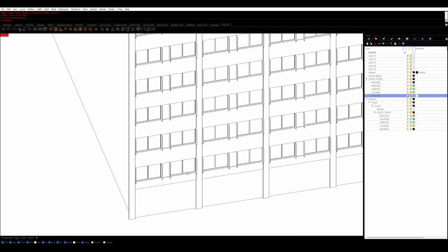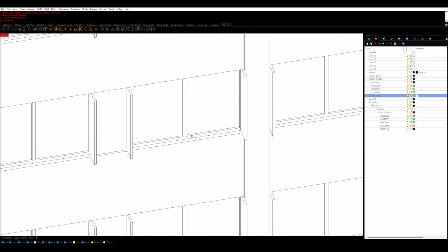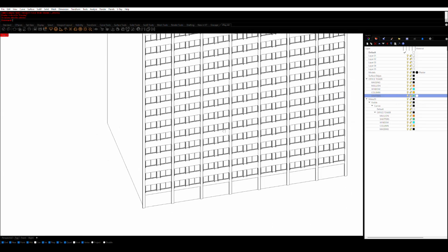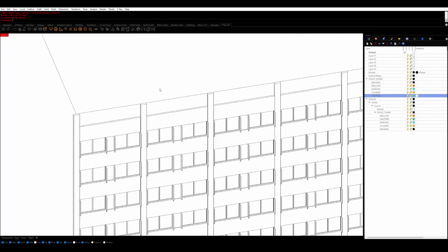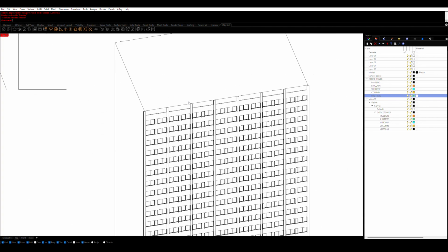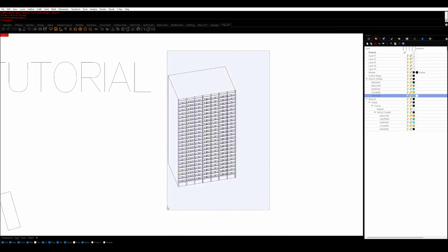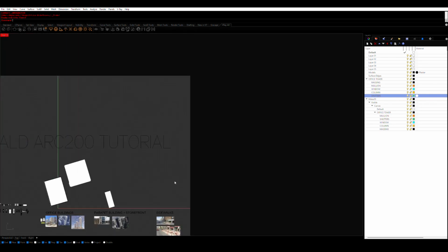And another thing that's important to consider is also the sort of thicknesses that you have set. So our mullions were actually quite thick, they were 3 inches. But at this scale, they do read very dark. And you can imagine that if you had the spacing any smaller, then it might just read as a very bold or thick line. So that's something to be cognizant of anytime you're modeling to make 2D and to produce drawings.